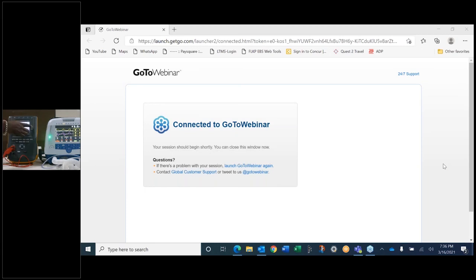Touch current, as I have told yesterday, we are going to use an aluminum foil which is wrapped on the body of the equipment. You can see we have wrapped an aluminum foil on the equipment and we are going to do the test on it.